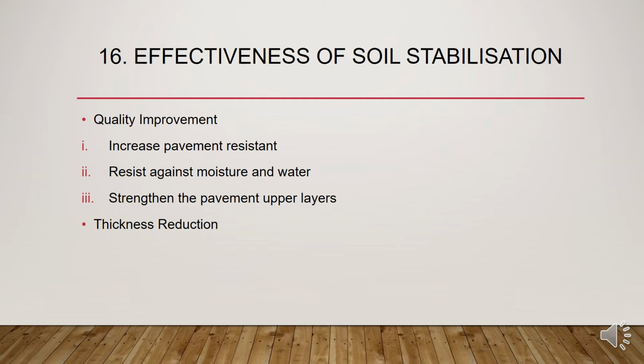Soil stabilization improves the quality of the weak soil, increases the pavement resistance, resists against moisture and water, and strengthens the pavement upper layers by strengthening the subgrade, as well as it reduces the thickness of the pavement, which is cost effective and economic.